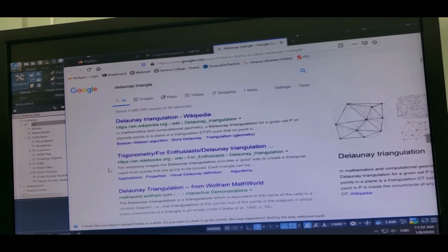And he created this mathematical method: if you have a lot of elevation points, and you want to create a representation of how the ground of these elevations looks like, you can create triangles within these points, and they have to look like each other the most. It will be the best representation of the real site out there. Does that make sense? You kind of understand?